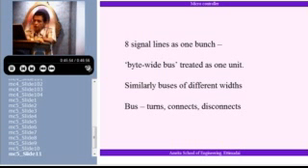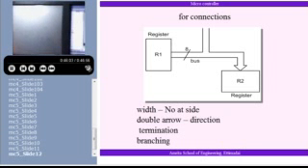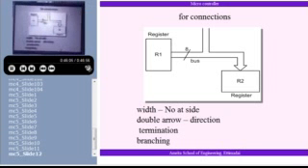A bus can be connected in different ways. I've shown here a register, R1, and another register, R2. This shows this line and the number, which show that this bus is 8 bits wide. This register has 8 flip-flops. It can store data of 8 bits. Now, I can take this data and give it to this register. This is an arrow.